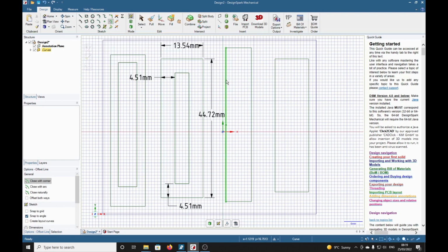Double click on any line of the rectangle, which highlights the whole thing, then just move inwards. So we can now type in a dimension for the shoulder distance. At the moment 2.17. Just type a 2 for a shoulder of 2 millimeters, and that's perfectly in the middle.